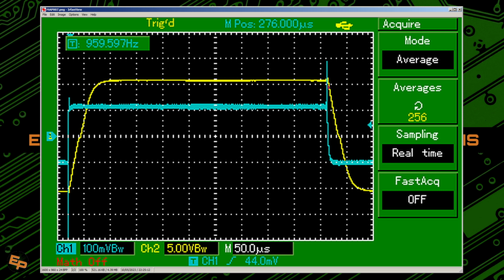And we see the same phenomenon happening again on the falling edge of the input signal. The output signal also starts to decrease at the same time, again with a certain slope, but that's beside the point. The point is we have both signals in sync because the op-amp doesn't have any transistor in saturation.